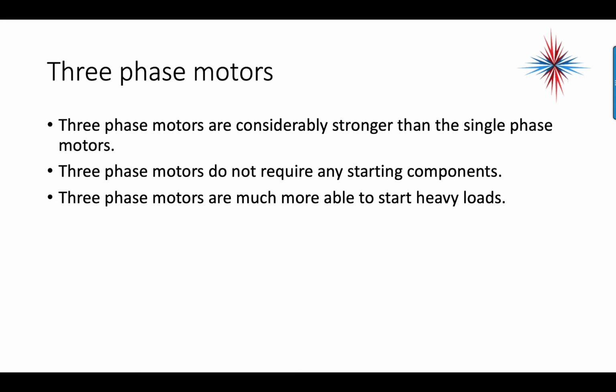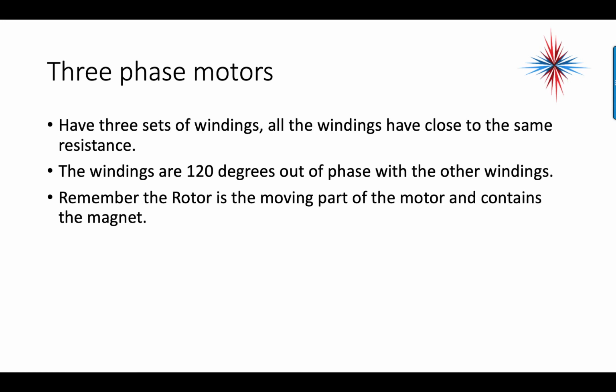3-phase motors do not require any start components. You will not see a capacitor on a 3-phase motor. Now, that doesn't mean that if you're going into a 3-phase rooftop unit, you won't see a capacitor, because sometimes the condenser fans and the indoor blower motor are not 3-phase. It might just be the compressors that are 3-phase. So just be aware of that. 3-phase motors are much more able to start a heavy load.